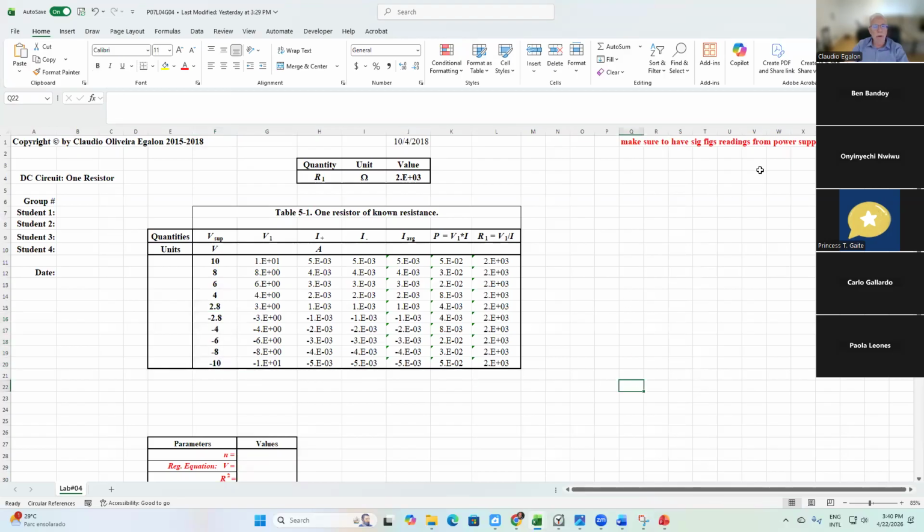And what we want to do, we want to verify Ohm's law by doing this experiment. Once we vary the voltage, we are keeping the resistance constant. We're not going to change the resistance whatsoever. And then we measure the voltage across the resistor, and we measure the current that flows through the circuit at 2 different points in the circuit. Okay, the current at 2 different points should be almost the same. Okay? And we do get almost the same, a very small difference only.